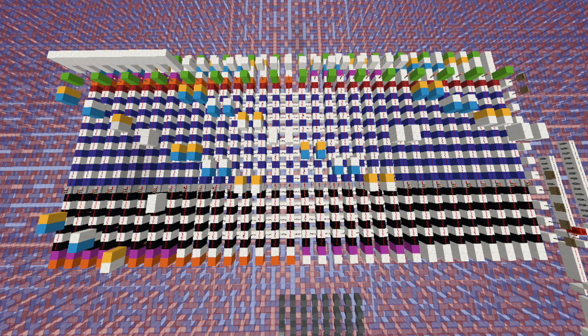And it just so happens that the least significant bit of the shift number, the first bit, will actually tell us if we're shifting an even or odd number of times. So we don't need to do any processing with that first bit, we can just send it directly into that adder shift bit. So the next thing we need to consider is how to get this barrel shifter to do the rest of the shifting other than just that simple one.